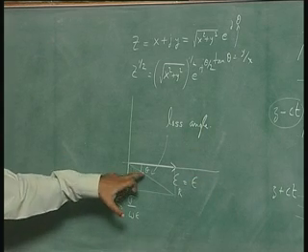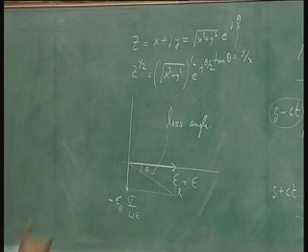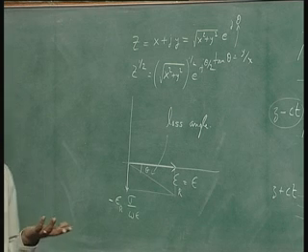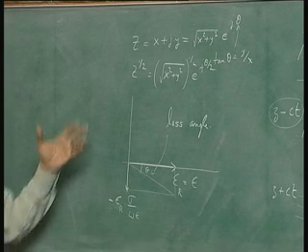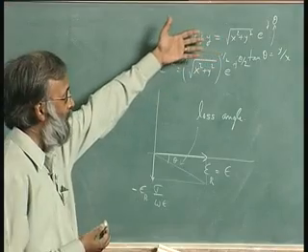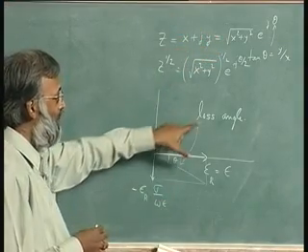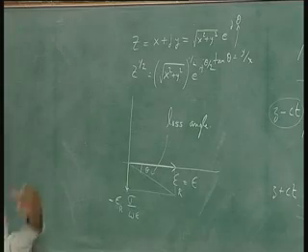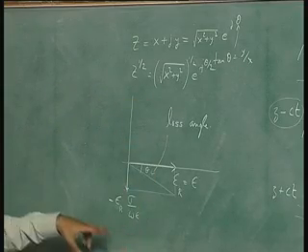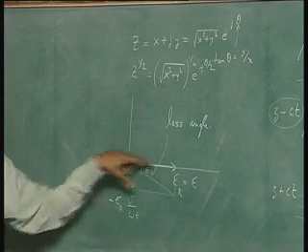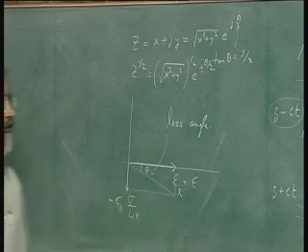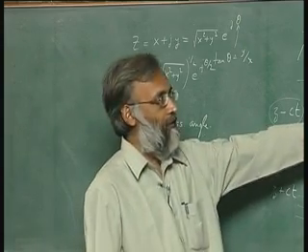And it is an important number to know, because when you look at material handbooks, they will not really tell you in the form that you will find these things in equations. They will tell you the loss angle of the material. Effectively, from the loss angle of the material, you are getting the imaginary correction to epsilon real. So, directly you will be able to write down this piece.